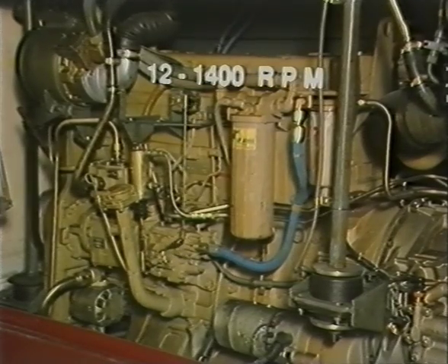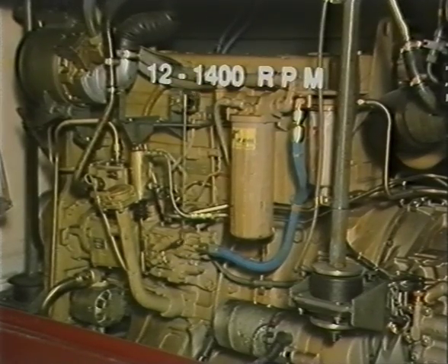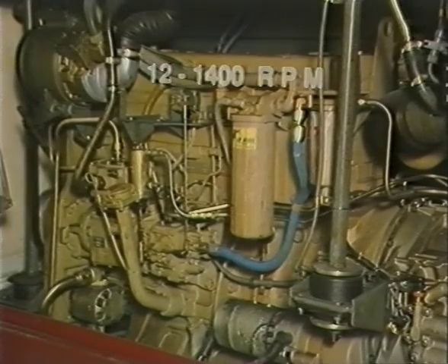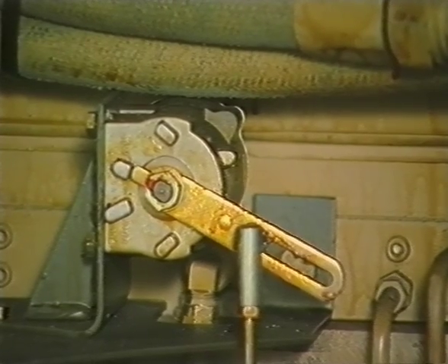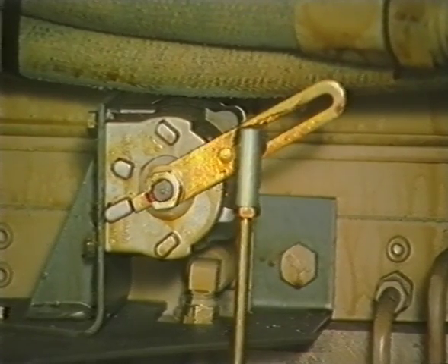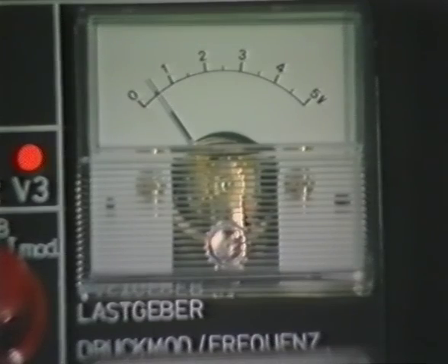It should achieve between 1200 and 1400 RPM during the stall test. Assuming these initial items are in order, first ensure that the load sender is set correctly, as previously explained. If the test equipment is available, the voltage at idle and full throttle can be checked. Half a volt at idle, 4 volts at full throttle.